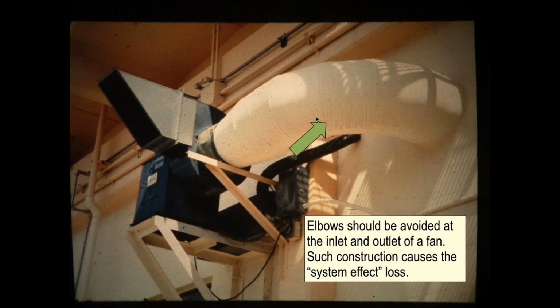You said it's direct drive. You could have direct drive, a fan hooked right to a motor. Your air conditioner in your home has a motor in it. When you turn that air conditioner on, two fans move. They're both hooked up to a shaft in the middle, one on the evaporative coil in the front, one on the condensing coil in the back. They run at the same revolutions per minute as the motor does, since they're both stuck to the shaft that goes through the motor.